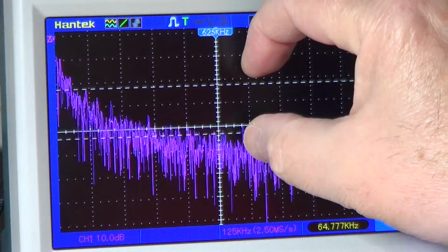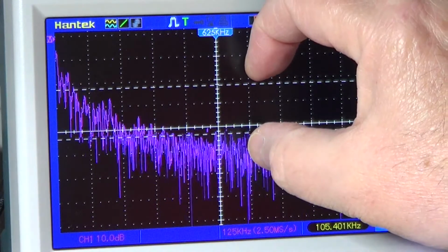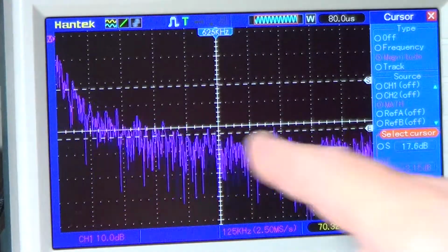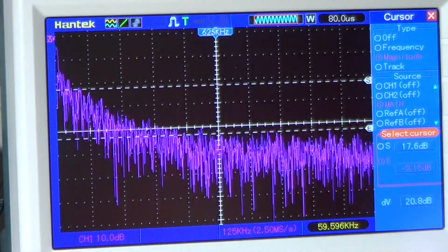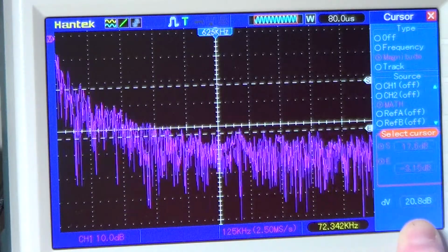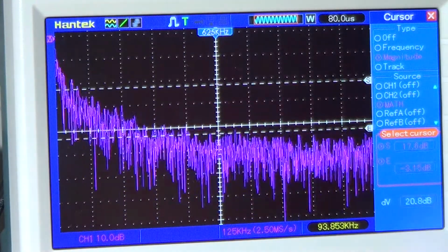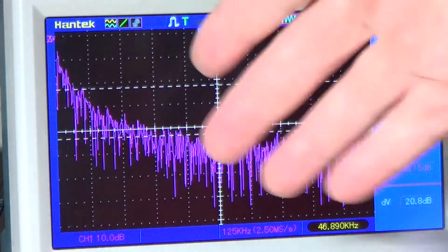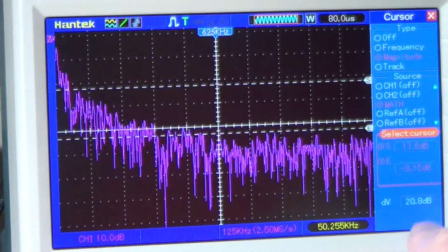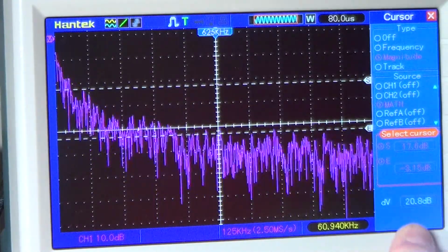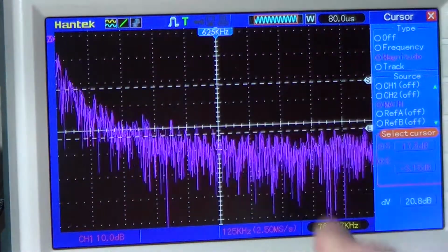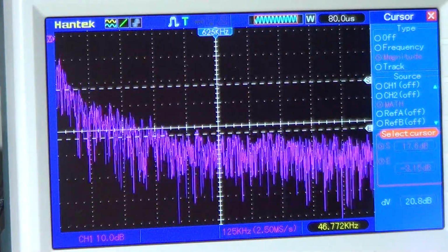So this is the drop in signal, so the attenuation of the system for a decade of frequencies, and we can read here the value. It's at 20.80 dBs, of course with the approximation that I made in doing this graph. So we can see that we have actually 20 dBs per decade if we do the measurement correctly.